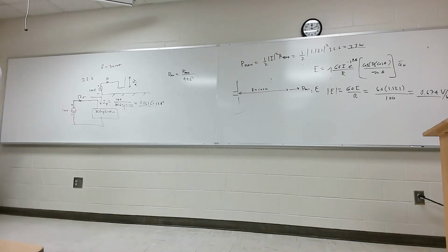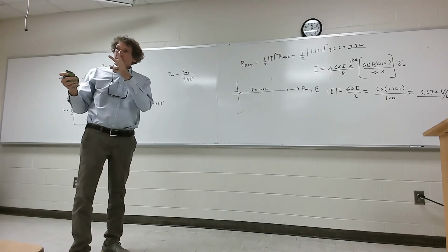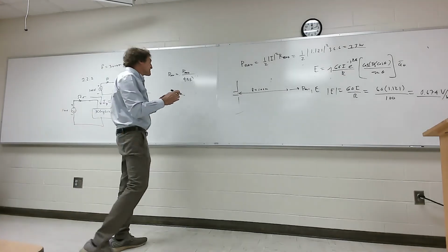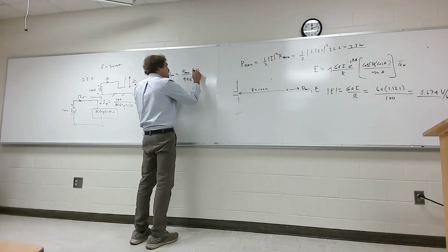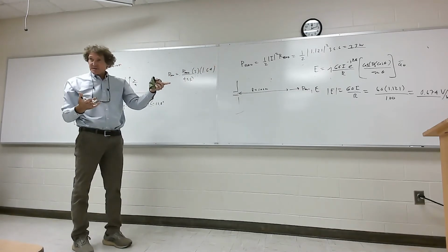Then you have to multiply by the gain, right? Now in our case, it's a monopole. So the directivity or the gain is 2 times the value of the actual dipole. Do y'all hear me on that? The dipole antenna had a peak gain of 1.64, right? The half-wave dipole. This will have a gain of twice that. So it's going to be 2 times 1.64. And there will be a maximum there because it's at 90 degrees.